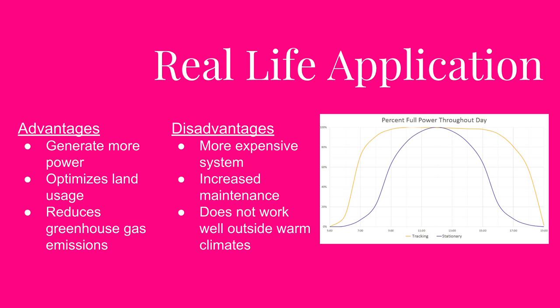Some disadvantages of tracking systems are their increased initial cost when installing the tracking system. Even with advancements in reliability, there is generally more maintenance required than a traditional fixed rack, though the quality of the solar tracker can play a role in how much and how often this maintenance is needed. Solar trackers are generally designed for climates with little to no snowfall, making them a more viable solution in warmer climates. Fixed racking accommodates harsher environmental conditions more easily than tracking systems.